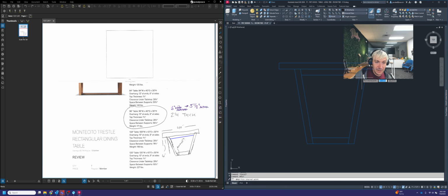So we're going to use that here, and we're going to click on each part that we want to make into a 3D part, just like that. When you're done, hit enter, and then you should be left with 5 polylines here. You can see that by clicking on them, that you are able to select those as solid rectangles instead of individual lines. The one downside to using bpoly, though, is that every time you use it, you're going to be left with the lines that are underneath still. It's kind of hard for me to see, but there are some loose lines that are sitting down there.